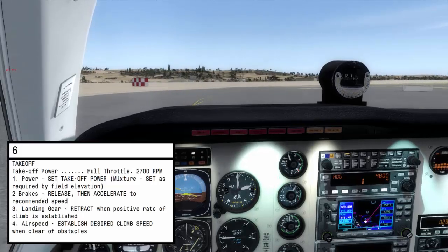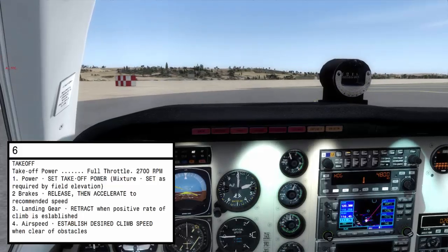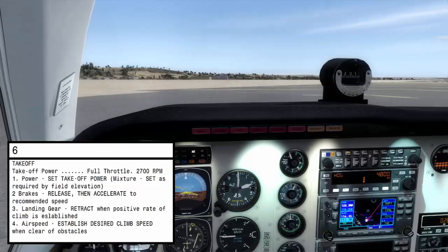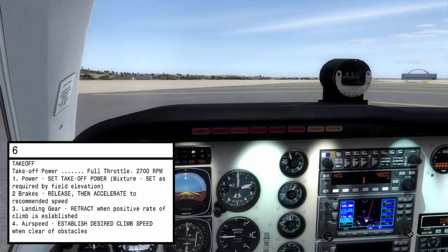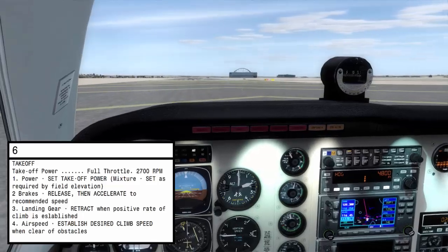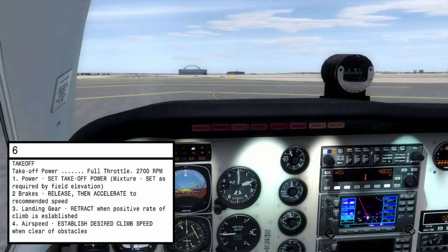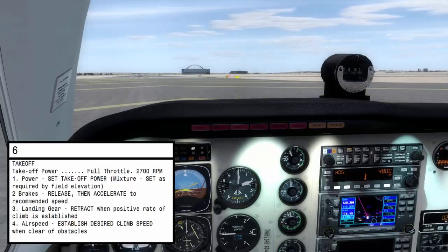Well, your joystick is properly configured, but when you take off, you need to have in mind that the aircraft will move to the right side or to the left side, okay, and that is a natural effect that occurs due to the adverse yaw. So we need to correct that with the rudder.